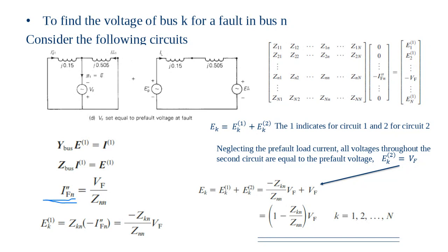Okay, so this is what happens here. If there is any fault, the circuit breaker opens to clear the fault, so the current will be zero, not high as we are calculating here, and then it recloses again, and then opens. A very short period, maybe just 2-3 cycles, 5 cycles.